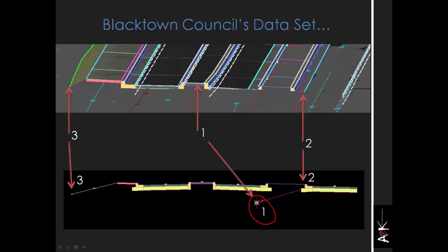We're then going to use a generic link to push everything over to this point here. That's going to allow us to jump from the center line straight across to the right-hand side of our road. We will then do a sequence of operations and project our way the whole way across the road using various strings as guidelines, get to the end, do our batter, and tie into that line. So the whole trick is starting in the middle, working to the right, and back across to the left.